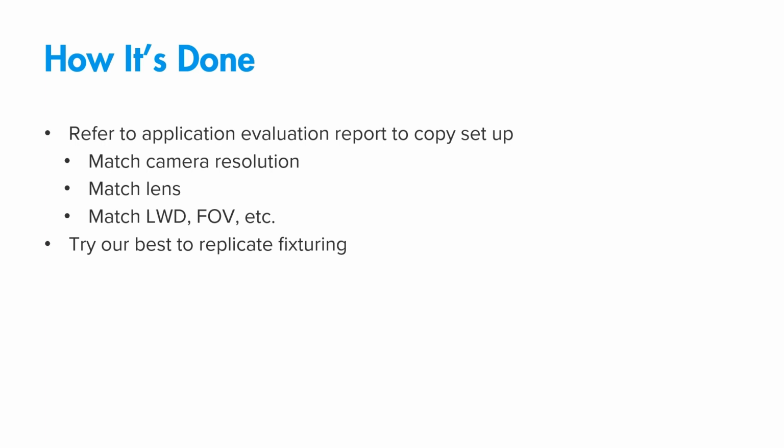so we were recommending a 5 megapixel. The second modification we made: a monochrome camera was also listed, but trying to find the best wavelength of light to use with the back of the pills with a monochrome camera was really difficult, because if it was a color, it helped some blister packs but hurt others, and if it was just white, it made most of the pills too gray to get enough contrast. So we found a color camera to be a better solution.